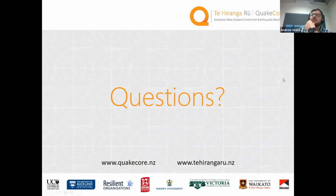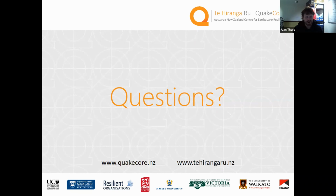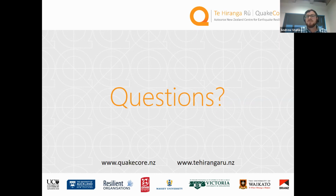I can talk to this a little bit, and then Liam could probably chime in. The troublesome bit with the NZGD is it's generally uninterpreted data, right? I mean, you're putting in borehole logs or CPT profiles. As you move into picking site periods, there's actually a little bit of interpretation on the part of the person providing the H/V curves, even more so with shear wave velocity profiles from surface wave testing. So I don't quite know how we handle that yet. Yeah, it's a difficult one. You almost need to be actually putting the interpretations in there. Yeah. And then the liability of what happens if someone uses my shear wave velocity profile that I've interpreted in their design and it does something. That's a tough trade-off. I think that people are still trying to figure out.